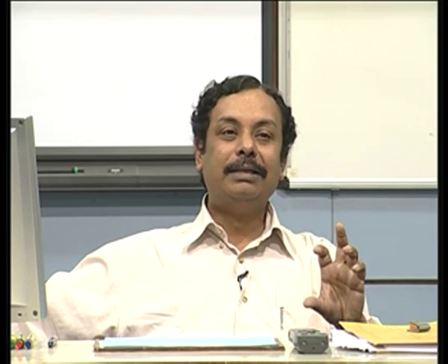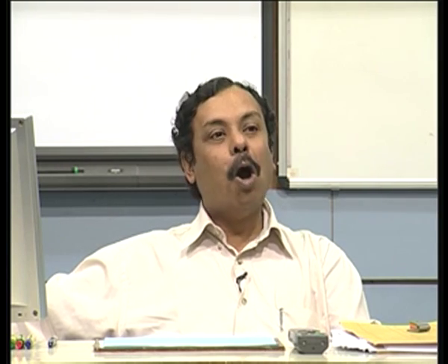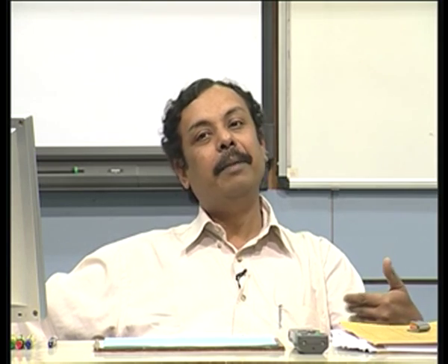And that is precisely the basic motivation for enabling wireless networks on a variety of devices and embedded devices today. They implement the 802.11 MAC protocol and spread spectrum communication to meet the requirements of the physical layer specification. On top of that, higher layers can also be implemented. An example is a camera: you can have even an HTTP server implemented on such a camera, and at the lower level it has a wireless link.